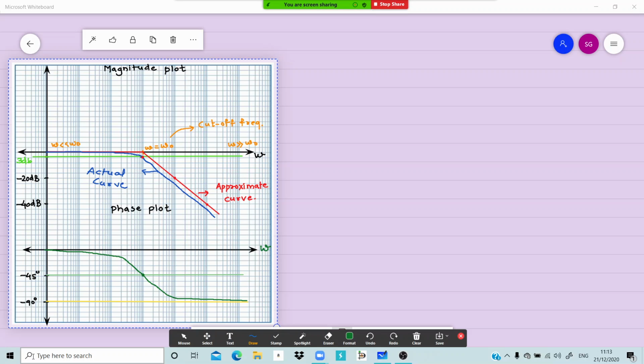If we are having, then what will be the Bode plot of that? Now we'll go for single real 0. If we have, then what will the Bode plot be? Keep in your mind, no matter how much you do mathematically or how much you draw, try to remember it logically. So keep in your mind, when it was a pole you got decreasing gain, right? When it was 0 it was increasing slope, not gain, slope, right? Gain also and slope also.